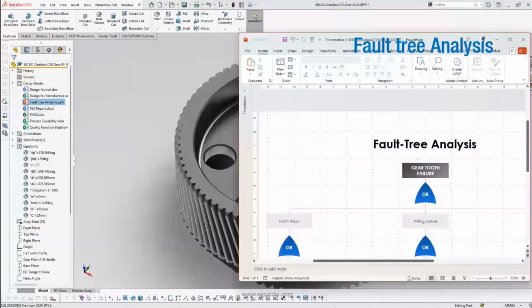If this is linked to a fault tree analysis already available on the system, then you can come back and say which are all the aspects that you have considered over here, and whether it is many factors coming together or only a few factors coming together. You can put these documents and ensure that people have complied with it. At the part level, again at the assembly level, selection of tolerance, so many different things. For example, if it is tooth wear and if it is pitting failure as a result of knocking because of backlash because of tolerances, you know where the measurable specifications are, right?